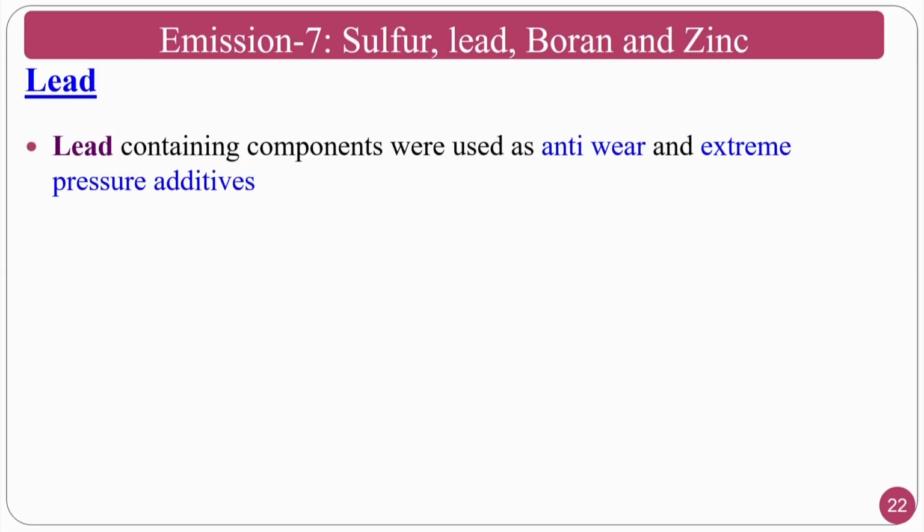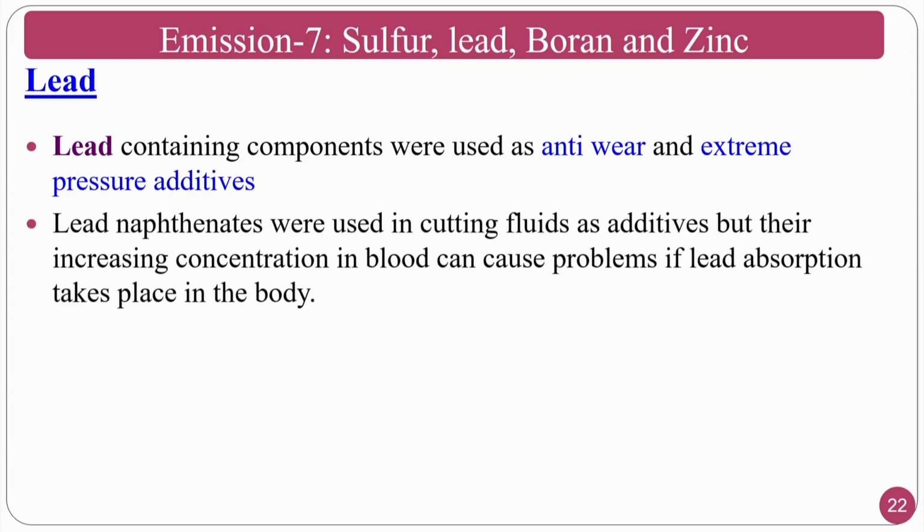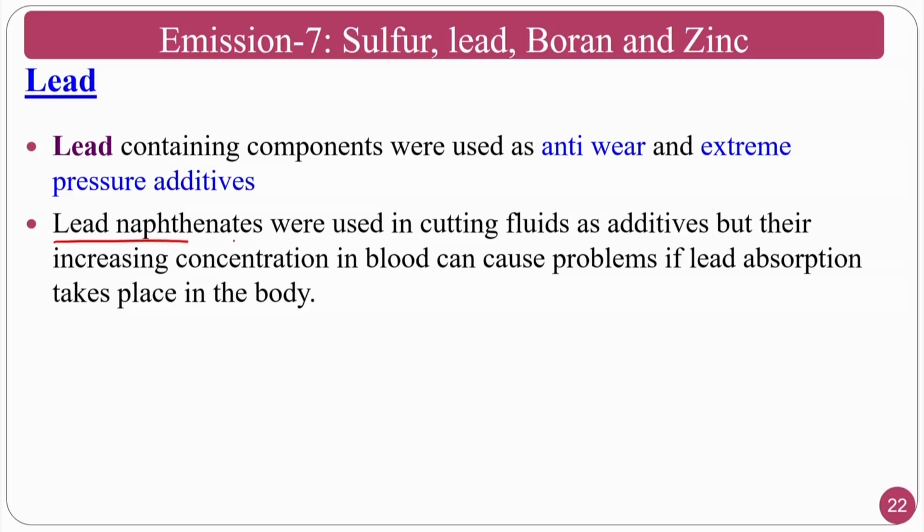Lead containing components were used as anti-wear and extreme pressure additives. Basically lead is a low shear strength material, so you can use it as a lubricant material. In that circumstance, tool wear and other things will be reduced, but it has an adverse effect. Lead naphthalates were used in the cutting fluid as additives, but their increasing concentration in the blood